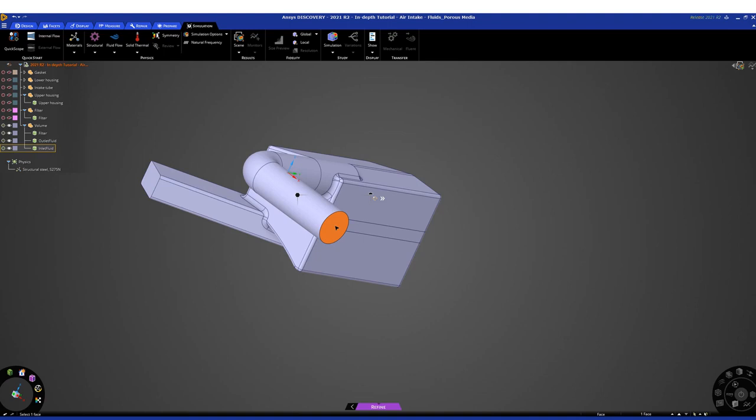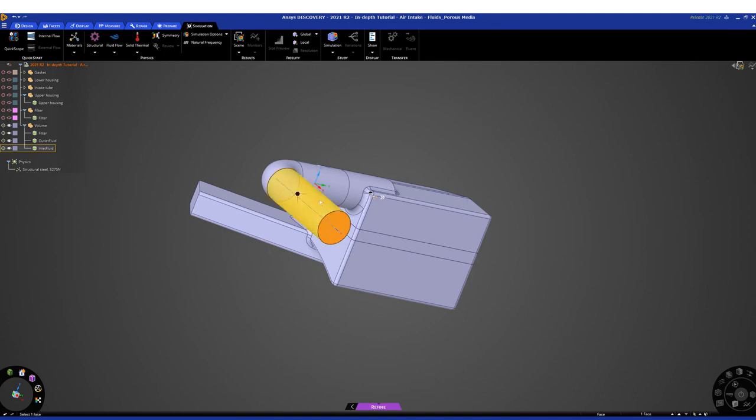So we're simply selecting the inlet surface, and then we have this black hex, and these tools here, which is called the halo, and this really allows you to access a lot of tools easily, and define if you would like to do a structural simulation, a fluid simulation, a topology optimization, or add monitor points, etc. So there's a lot of features in this.